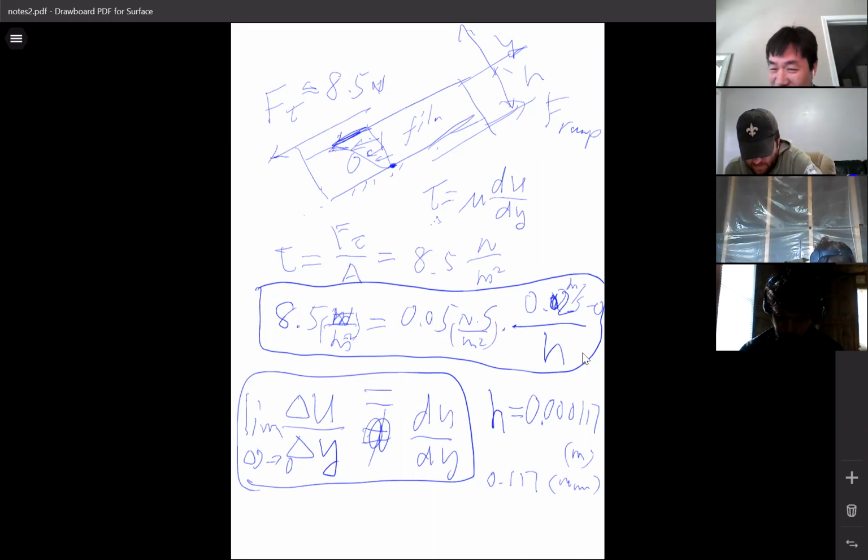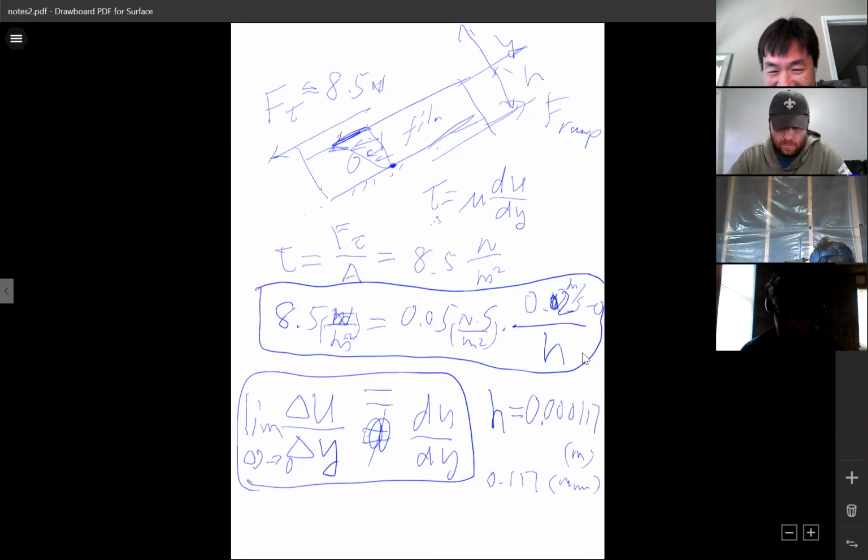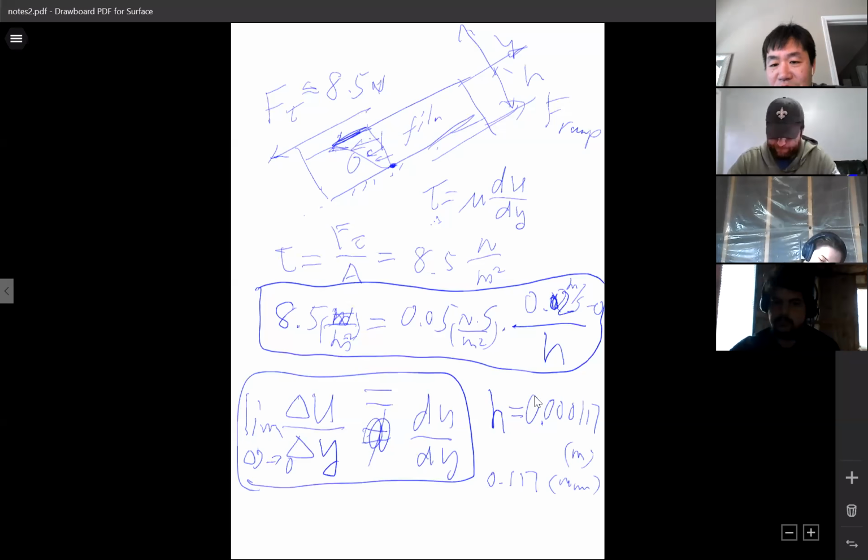Okay, so I meant to say increase. My bad. Increase? Why is that? Because if you increase the amount of film, there's less resistance from the ramp that's going to be applied to the board. Okay, let's come back to what I wrote up here. I like what I wrote down here. It's very clear engineering steps for this problem. Can you use the equations we use to explain why, if you want to increase the speed of the board, you have to increase the thickness? Which equation tells that?